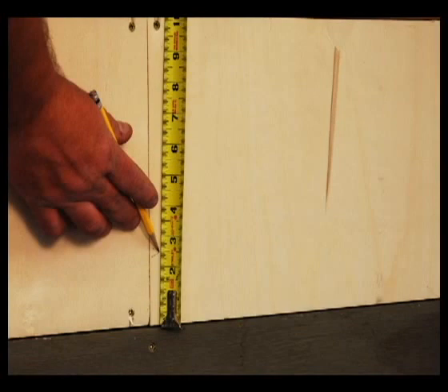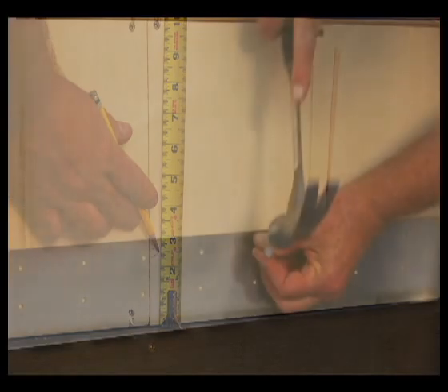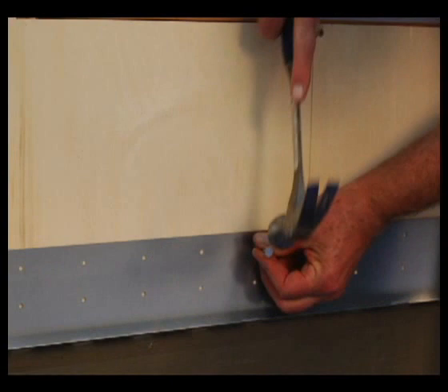The top of the 3.5" back flange of the L&R weep screed should be located and nailed 2 to 2.5 inches from the bottom of the sheathing and transition down over the top of the foundation wall approximately 1 to 1.5 inches. The back flange should be fastened to the bottom of the wood sheathing only and allowed to move separately from the foundation wall.